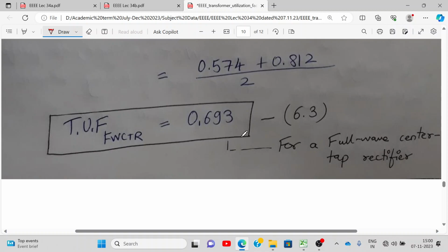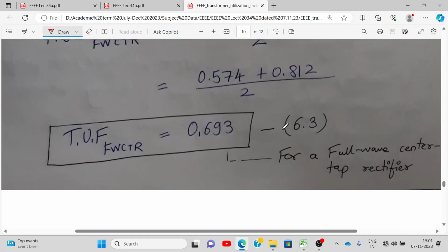So that means which is the best rectifier? Whatever you have studied, bridge rectifier. Now I can ask you one last question. Compare half wave rectifier, full wave center tap, full wave bridge rectifier. First point will be the circuit diagram. Second point will be how many diodes are conducting. Third point will be their output average current formulas, output RMS, ripple factor formula, TUF formula. What else is remaining? Rectification efficiency formula. It's different for all three, I mean, for two of them it's the same. Then the PIV rating of the transformer, that is also the PIV rating of the diodes. They are also different. Okay.